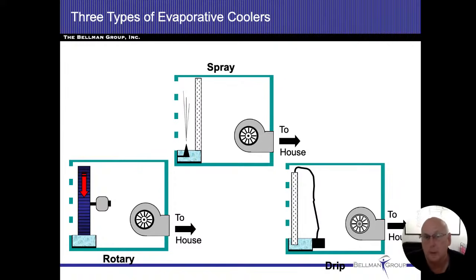So it's hard for us northerners to understand this, but with these evaporative coolers, they run with high flow air, big ductwork. You actually keep your windows open when you're doing this. You blow the humidity in the house. That moisture evaporates because of the very dry climate that they live in. And as it evaporates, it absorbs the heat of all the objects in the house, including the human beings that it touches. And they actually work fantastic.